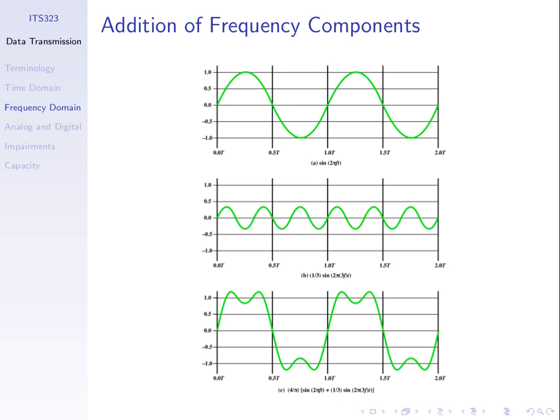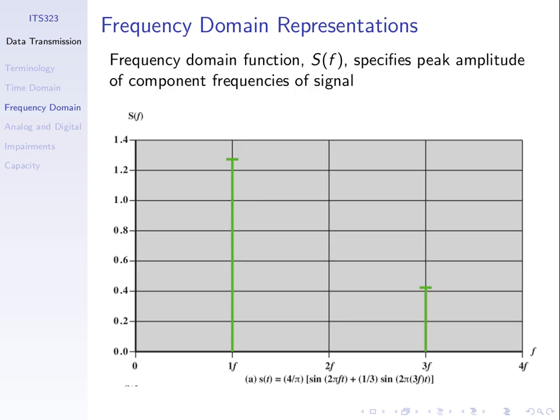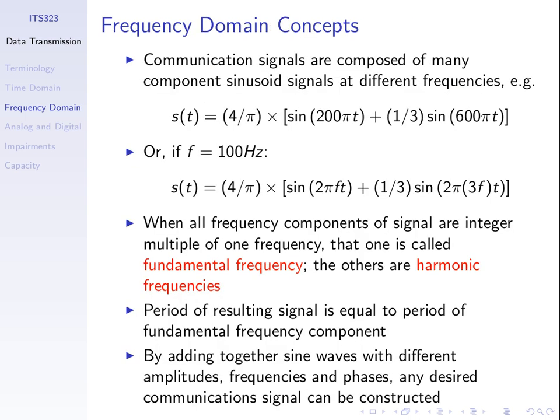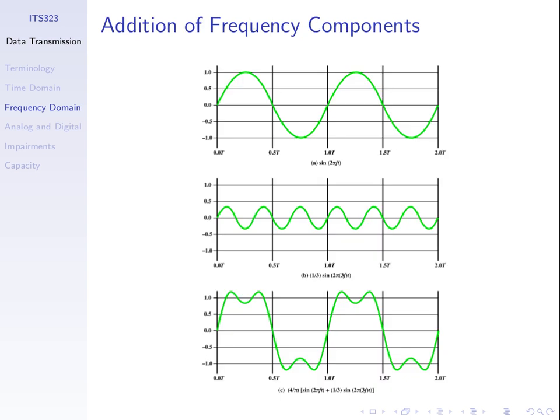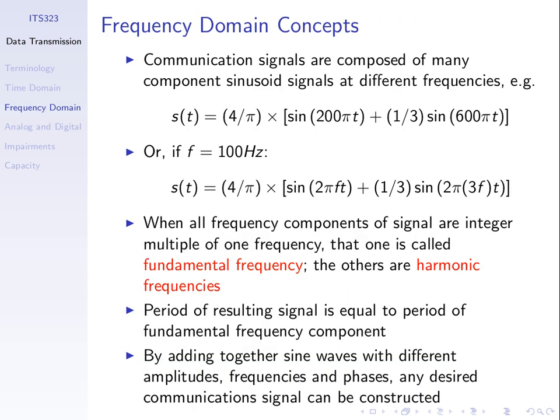In the exam, if I give you the same signal equation, can you plot this? Yes, you can, because you identify from the signal equation the frequency components of 100 and 300, the peak amplitudes, and simply plot the two impulses. So dealing in the frequency domain is generally, for the things that we want to look at in terms of signals, often quite easy.